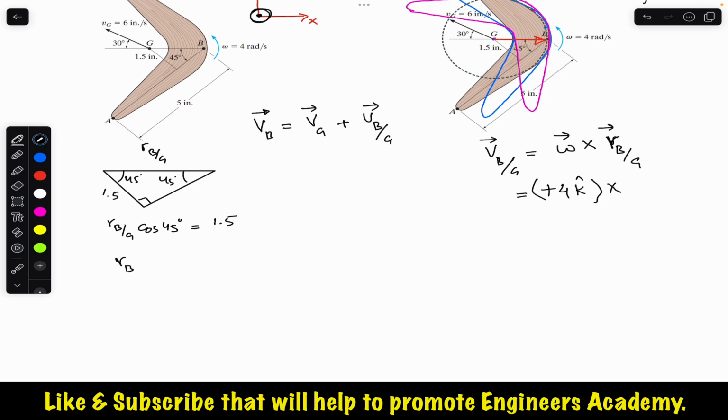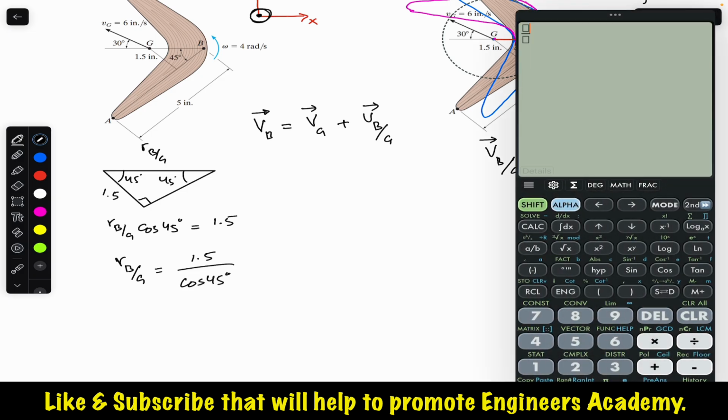So RBG will be the magnitude of the relative position from G to B, or we can say that the position vector from G to B is 1.5 divided by cos of 45 degrees. So this is 1.5 divided by cos of 45. This gives us 2.121, and this will be in inches. Remember, since this is in inches, so this will be in inches as well.